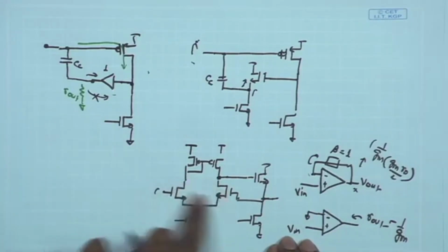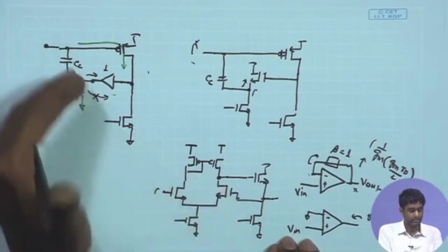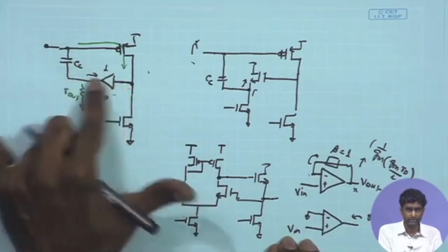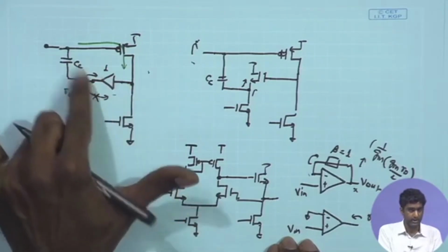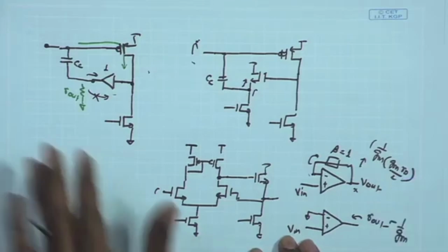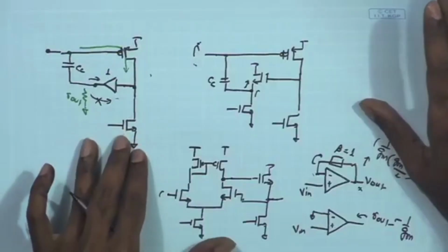We can achieve similar bandwidth at the cost of lower gain and still achieve low output impedance and a good buffer functionality for this particular unit, so that the effect of the zero is getting eliminated. So, this is one particular technique which we can employ in our design to arrive at the cancellation or elimination of the zero. Now, let us look at the second one.